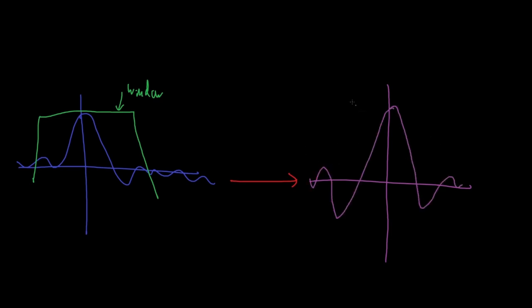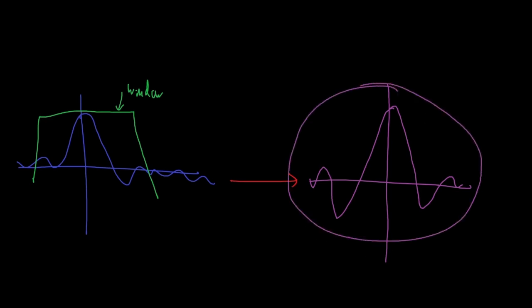And this is all you get, a finite impulse response. That is all a window function does. It constricts the time for the impulse response. It prevents it going from infinity to minus infinity. Keeps it to a certain point.